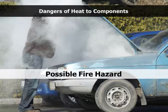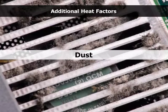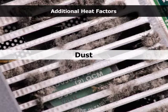And within a computer, fires can be caused not just by electrical problems, but an excess of dust, a great deal of heat, and then obviously the air to go with it, and then you can have a Class A or Class C fire depending on how it ignites. And there are also some other heat factors that you can think about with relation to a personal computer system. First, there's dust. When dust clogs up the various vents of the system, it can actually prevent cooling from taking